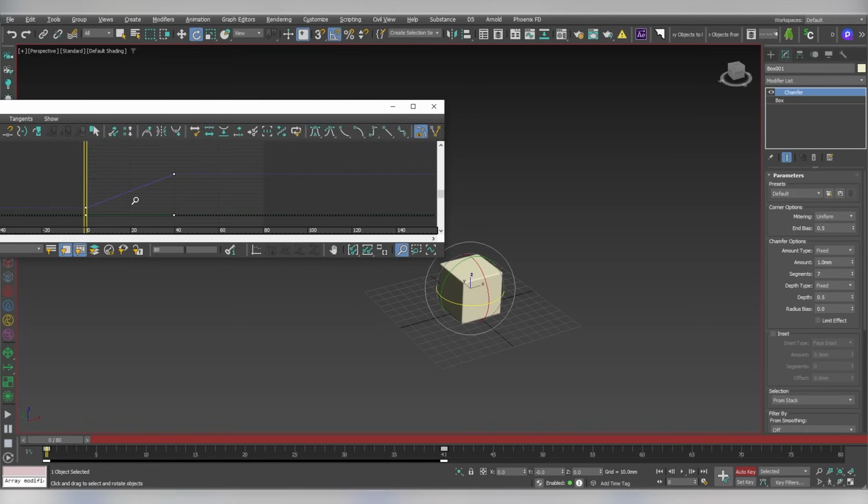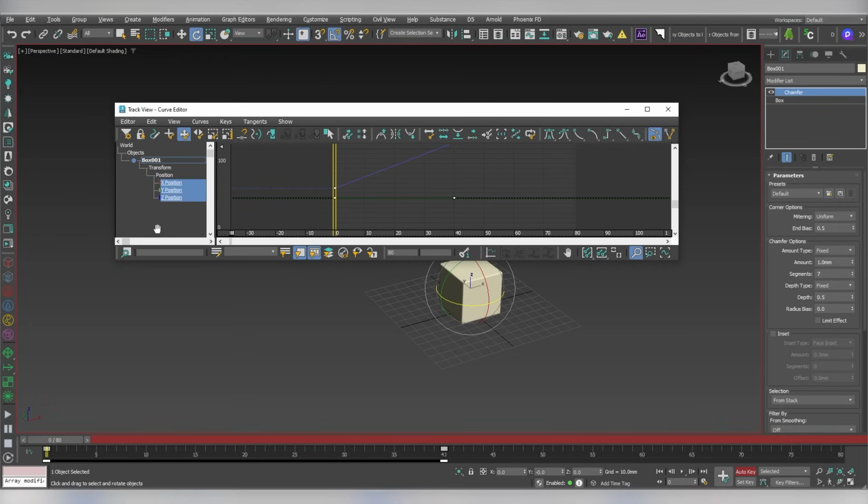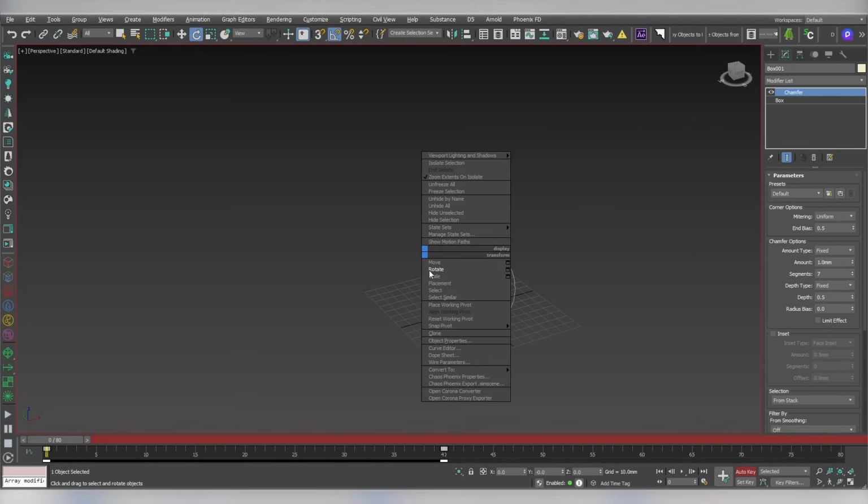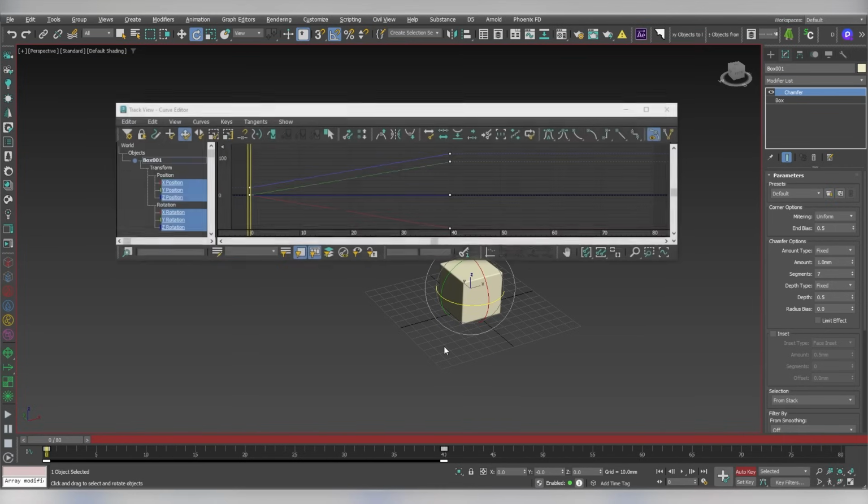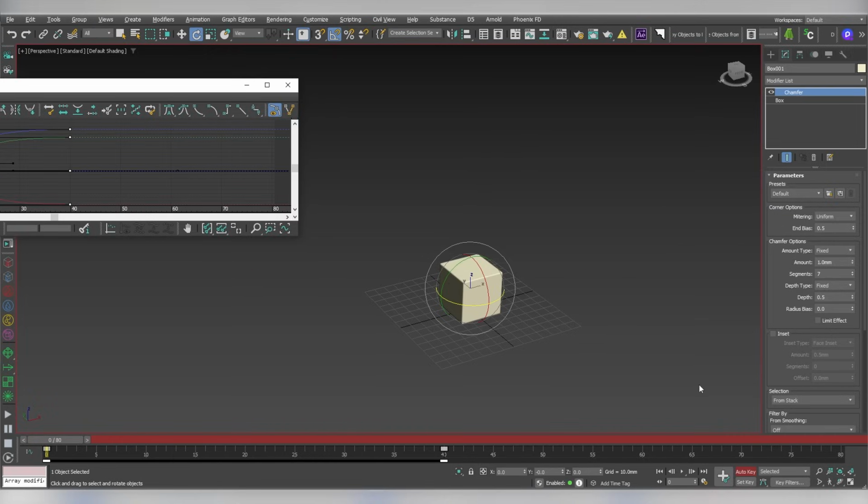When I look at the curve, I can't see the beziers of all keyframes. This is why in such cases, I recommend closing and reopening the curve editor. As you can see, all the animated parameters are now visible here. Click on Auto Bezier and increase the curve value by clicking Scale Tangents up several times. Now let's play the animation again. It looks much better now.